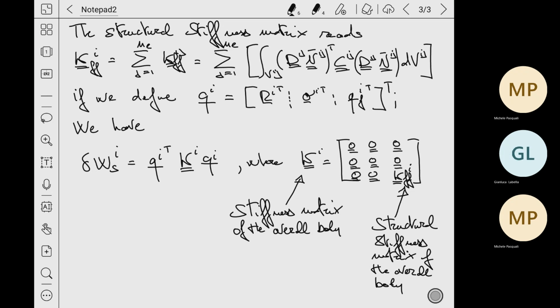On the other hand, you have inertial effects that vary with respect to the orientation and position of the body with respect to the inertial frame. And that's why you get a highly varying mass matrix. So depending on which of the two formulations you adopt, you either have a variation induced by inertial effects or a variation induced by a variation in the mutual orientation of the external forces acting on the body. Okay. All right.